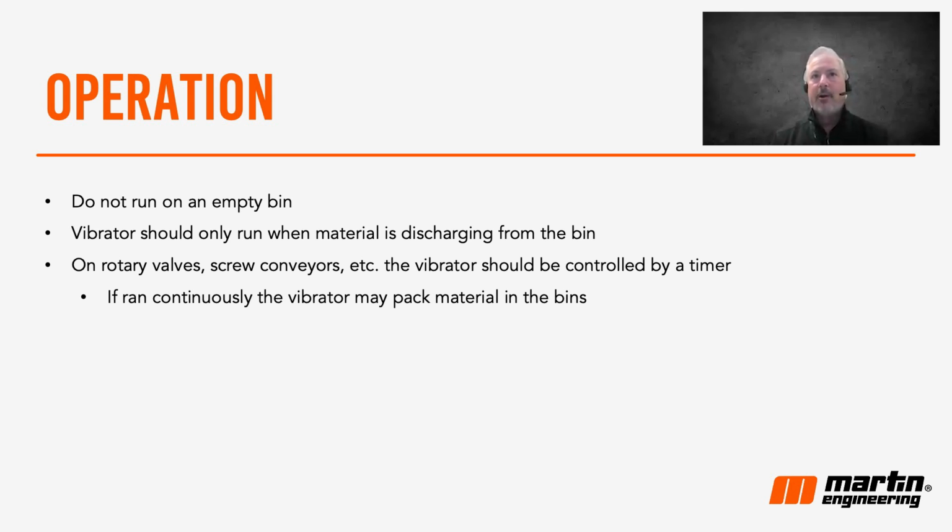And never run a vibrator on an empty bin. Just talked to a guy yesterday who had some issues with the vibrator tripping out often. What we found was, even though rigidly mounted, when there's no resistance on the other side of the wall, the vibrator is overforced for an empty void, increasing the amp draw and keeping it tripping out.